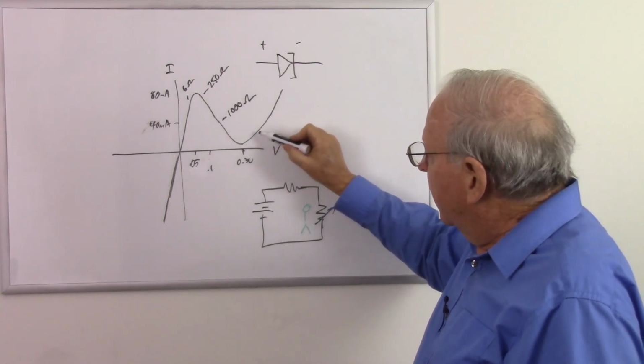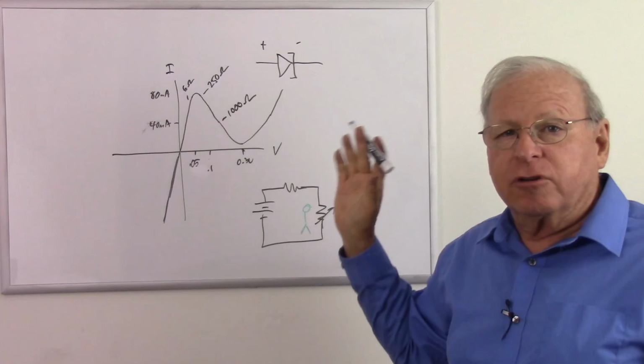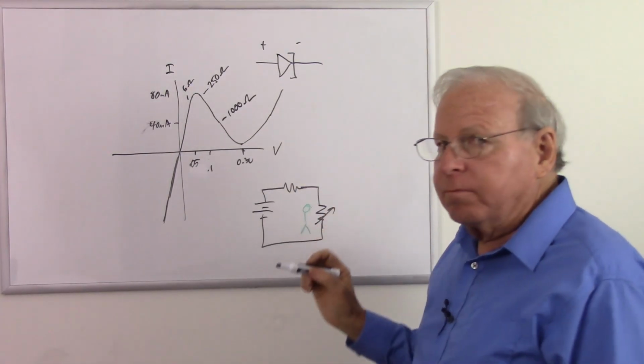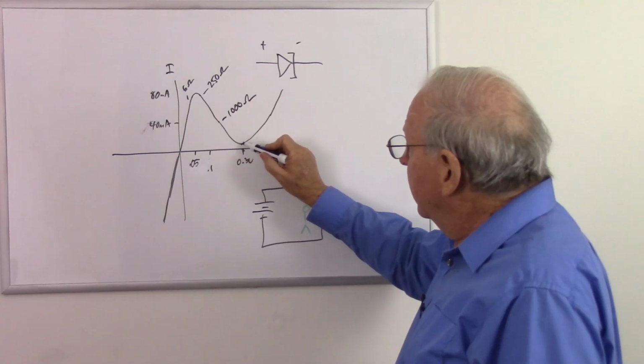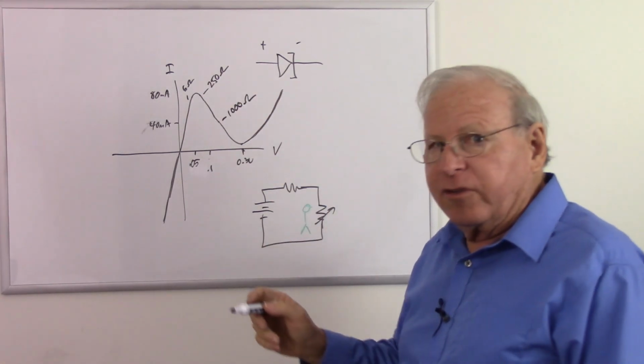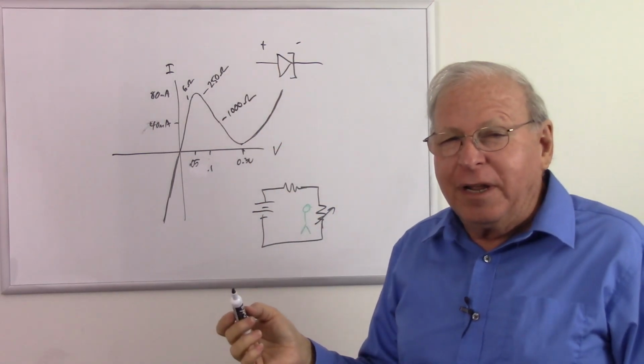And it's going to pretty much follow a diode curve, and this particular diode we looked at was a germanium tunnel diode, so it's going to have this point at about 0.3 volts. So nothing really mysterious there. We have a region here called negative resistance because as we increase our voltage, our current goes down.